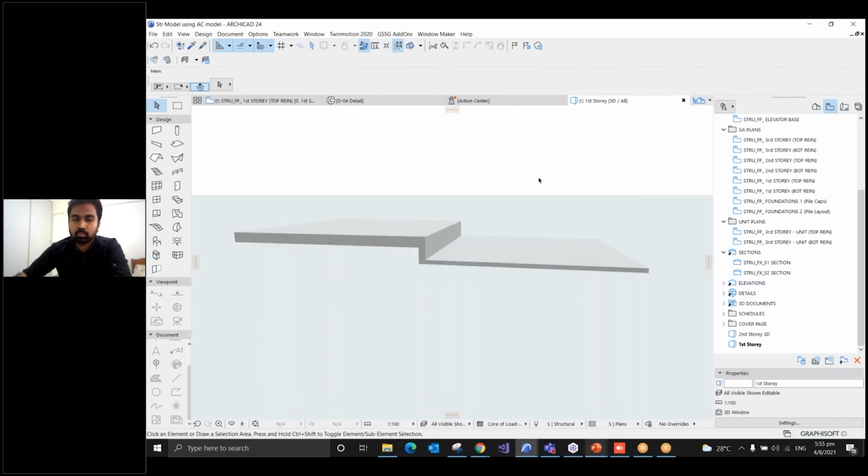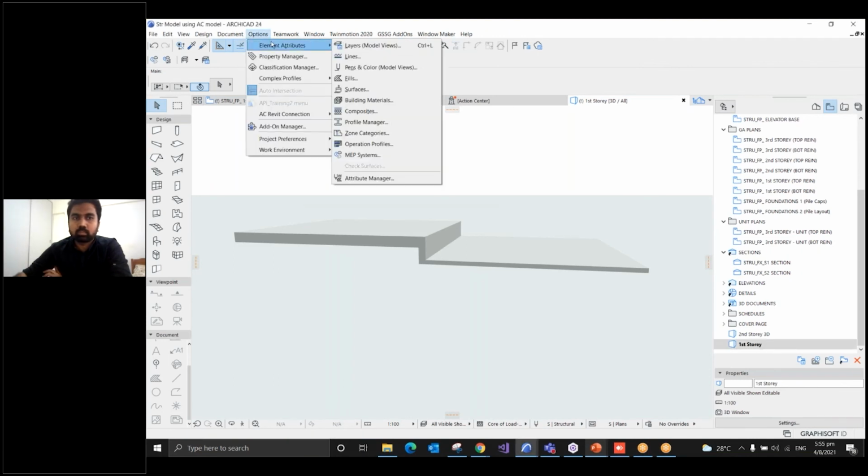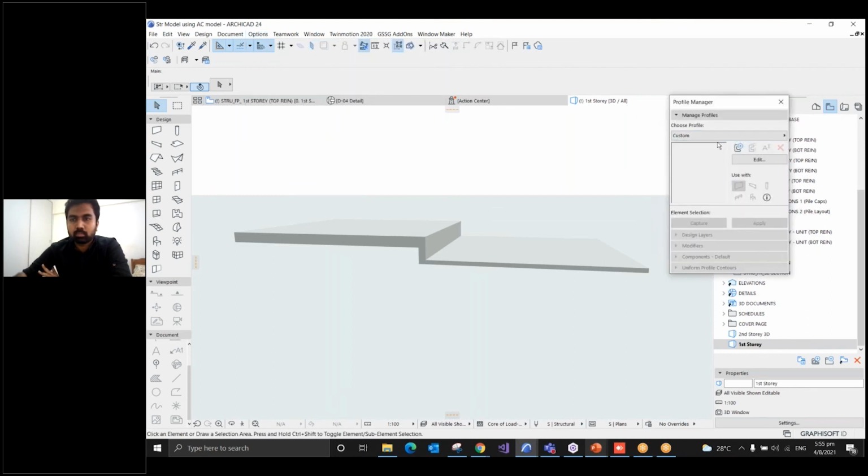So at the moment, for the drop slab, one option is to do it with a morph, right? The other option, if it is straightforward like this, is to draw a cross-sectional profile with finished layers and all those things, and extrude it. So it's kind of a workaround. You can come up with different options and try. It depends on the situation. Yeah.